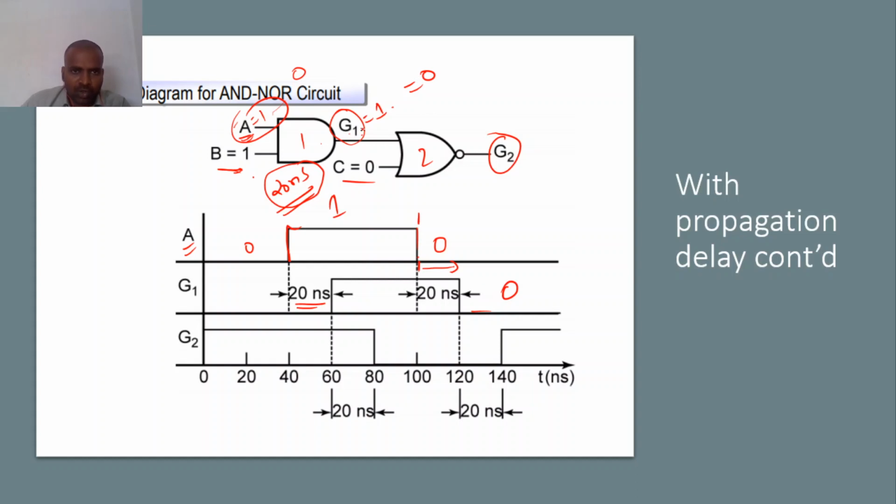Okay, right. So this G1 is having 20 nanoseconds delay. Then another gate is there. So here one input is applied 0. This gate is also going to produce the result with the 20 nanoseconds delay, because here it is already delayed by 20 nanoseconds. Here there is no delay, delay is equal to 0 seconds. But due to this G1, it is also going to produce with 20 nanoseconds delay.